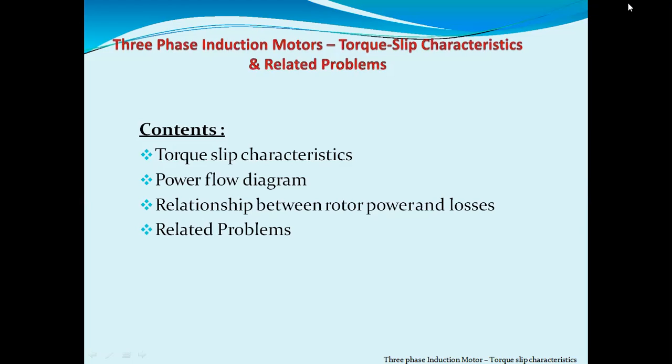So here we are saying torque will depend mainly on three factors. The first factor is the magnitude of the rotor current, which we take as I2. Torque is denoted by the capital letter T, or we can write the letter tau, which is a T with an inverted J-like symbol. Then torque will depend on the flux, which we denote by the letter phi.